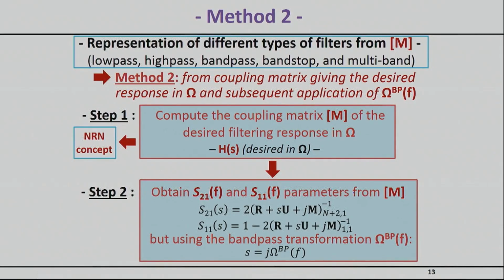In this lecture, we're going to focus mostly on the second technique, which, as I mentioned, has some advantages, primarily because it preserves the coupling diagram. And the reason this technique preserves the coupling diagram is because we actually compute the coupling matrix based on the desired filtering response in the normalized frequency domain.